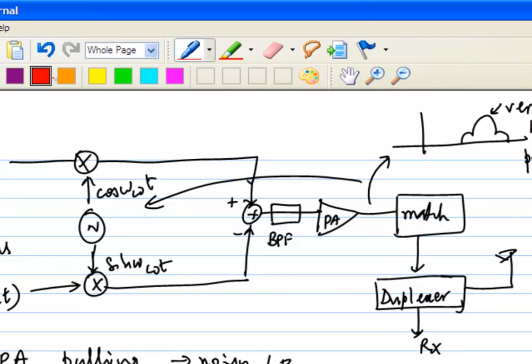See, on the assumption that if we mix these two, we get some gain. But why do you care about the gain? I mean, consider the entire feedback loop. Because of offset, I get some attenuation. What feedback loop are you talking about? This parasitic feedback. So when you offset these two frequencies, there is attenuation. That's right. And there is a gain here. This gain offsets that attenuation. What gain do you have here? Conversion gain. Actually, you don't care about conversion gain here, right?